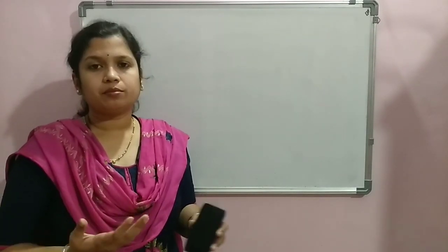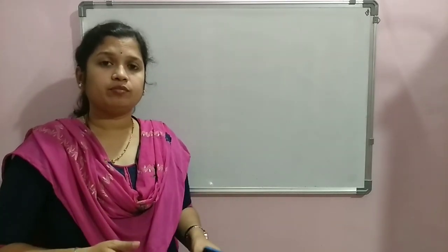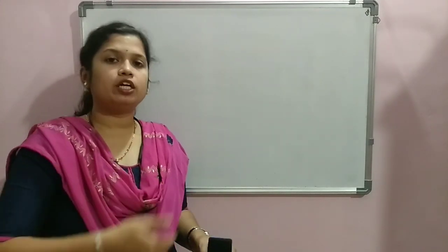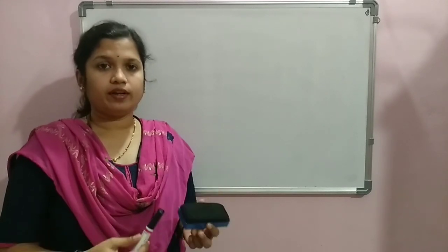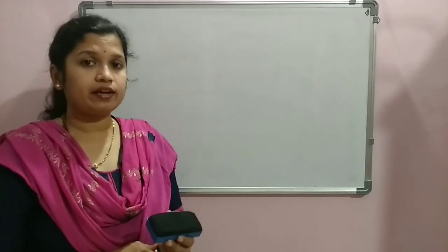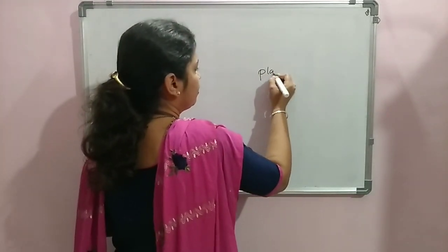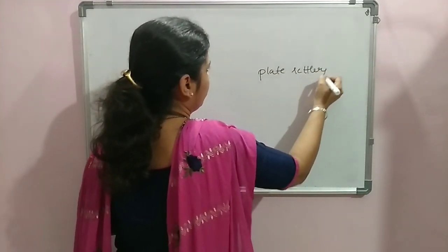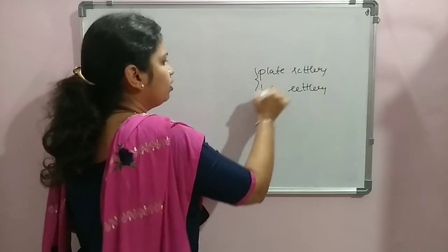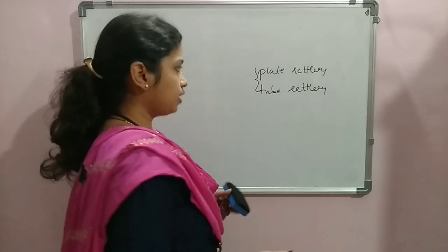and it also requires a large detention time, which is actually a waste of time for us. A lot of time also has to be given to clean and maintain the sedimentation tank. In order to overcome these disadvantages of the old and outdated method of sedimentation, we came across new types of settlers, or sedimentation tanks, which we call plate settlers and tube settlers. These concepts overcome the disadvantages brought by the typical sedimentation tanks, the old method of sedimentation.